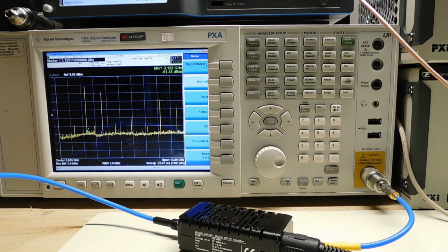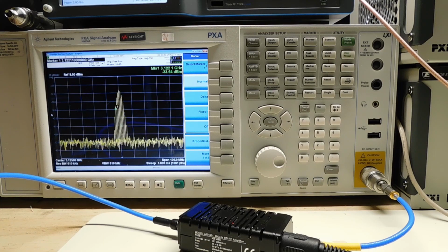Let's zoom in on some of those. So let's change our center frequency to 3.12, and you can see the modulated pulse there looks good. Amplitude is excellent. We haven't seen much of an amplitude degradation by using the digital up converter. So this is in essence in the first Nyquist zone of the instrument. We can go higher to the next Nyquist zone, 4.875 gigahertz.